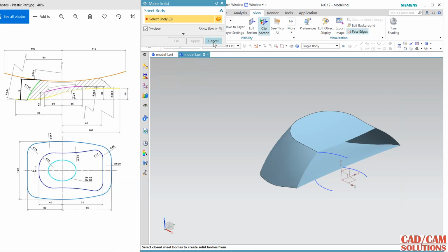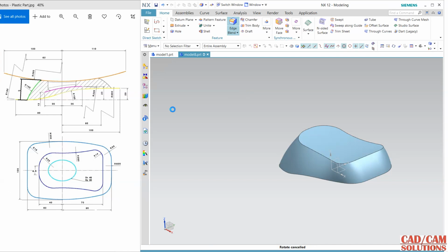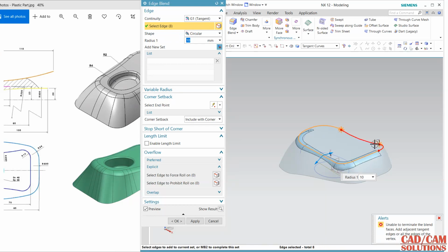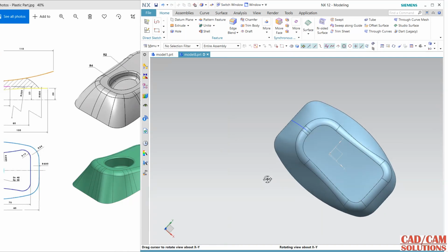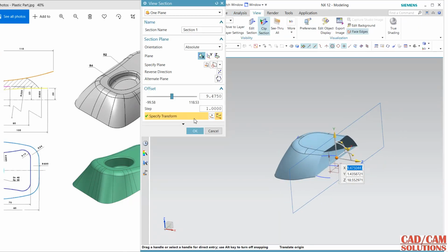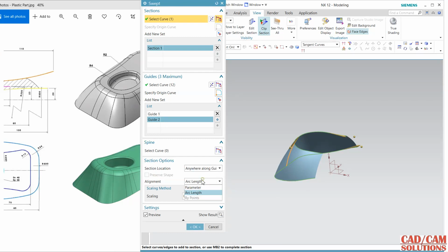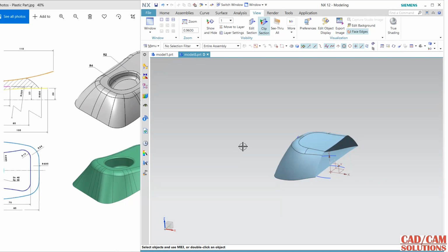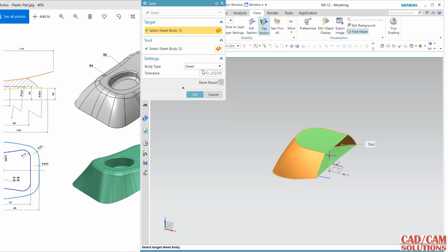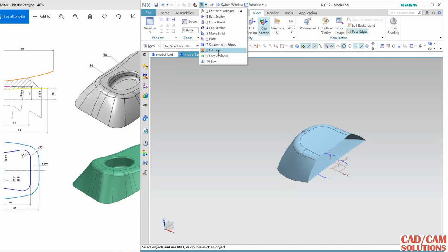I'm trying to select this, but it is not selecting. First, I'm going to apply the fillet, and the fillet is 10 on this outer. Okay, and from view, say this, it is still hollow. Go to swept. Okay, change this. Now in sew sheet and solid. Okay, no, it is not. Again, I am using make solid.